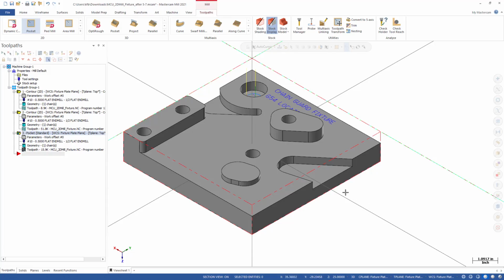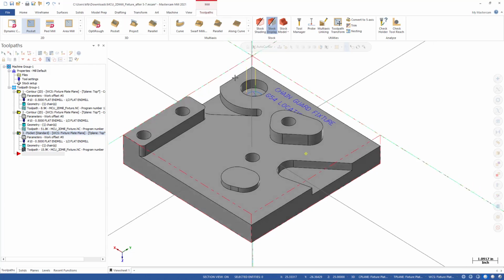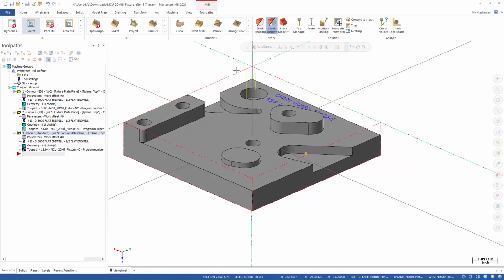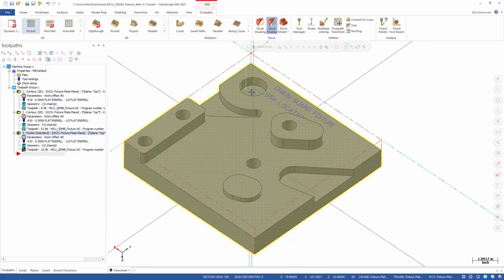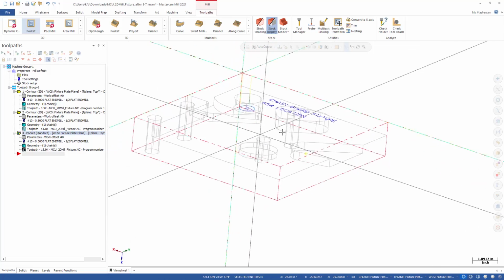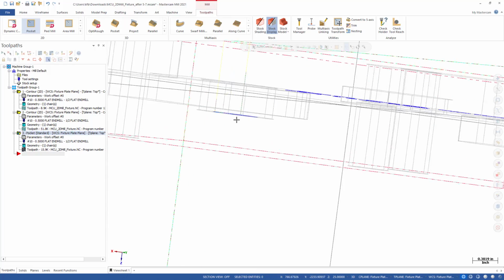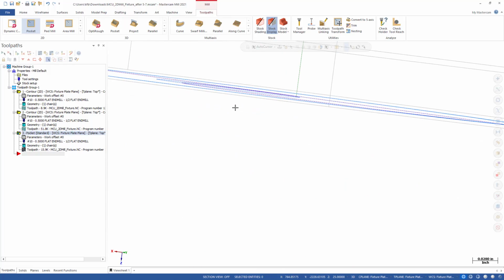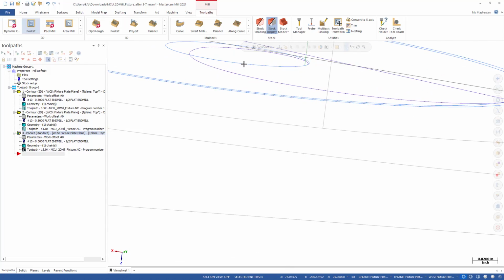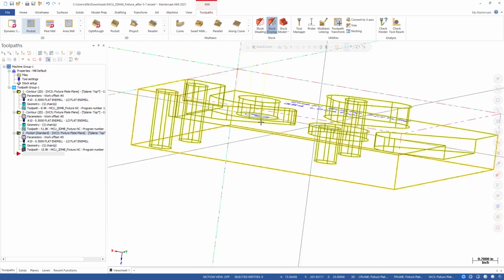The beauty here is we can always make changes. As you can see, the toolpath enters into the part, machines it out, and then retracts. The yellow portions of the toolpath represent the rapid movements, and the blue lines are feed movements. I can also turn on my wireframe display so we can take a look at this a little closer to see if we have any appropriate motion here. In this case, it didn't look like our helical move worked, so let's zoom out and briefly adjust that.